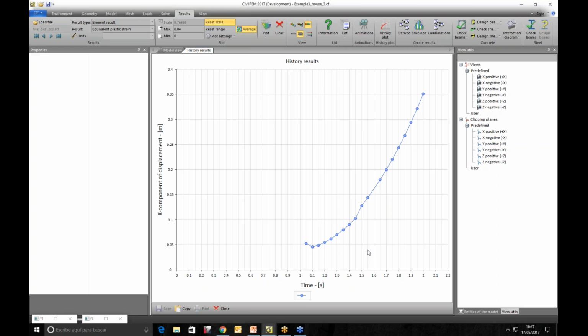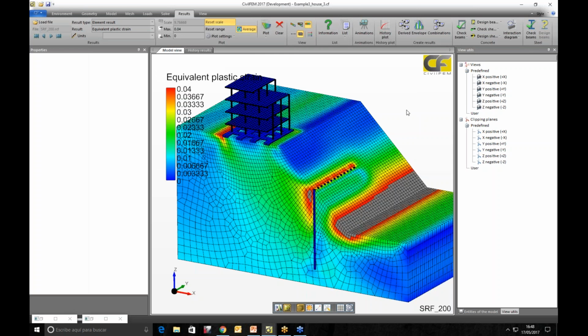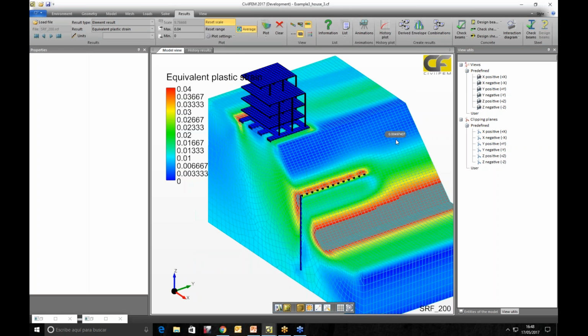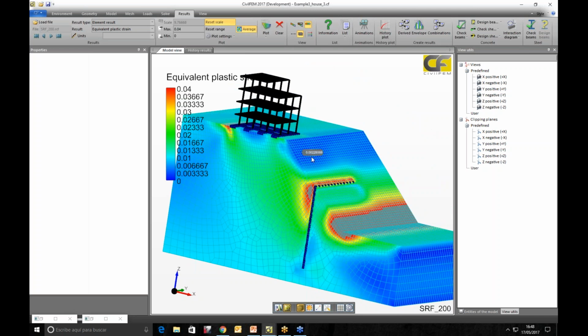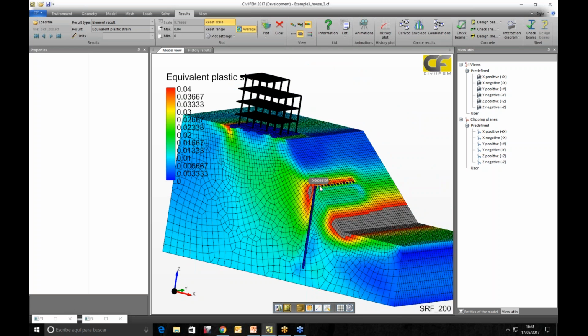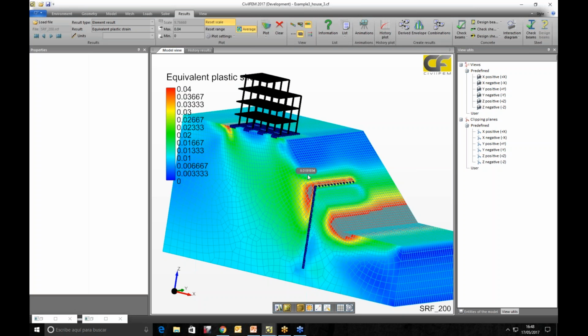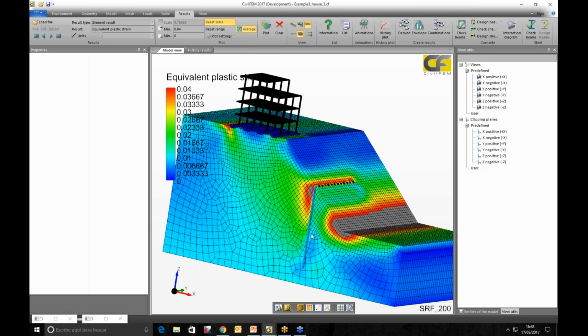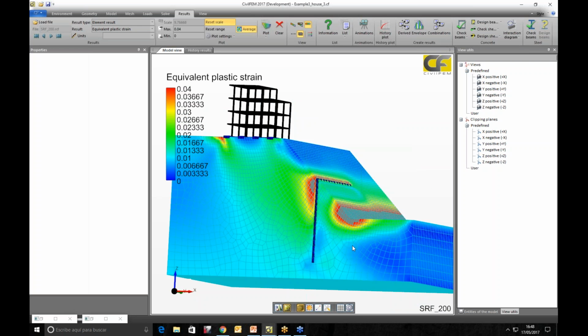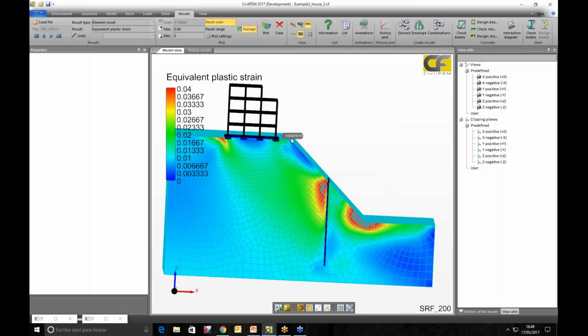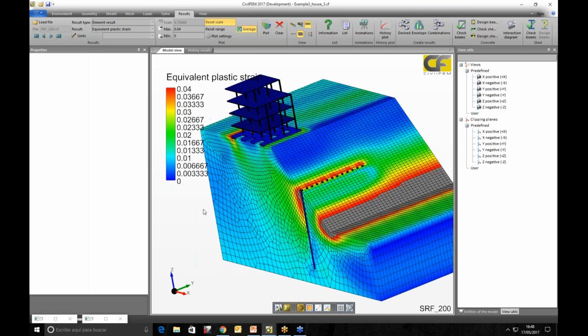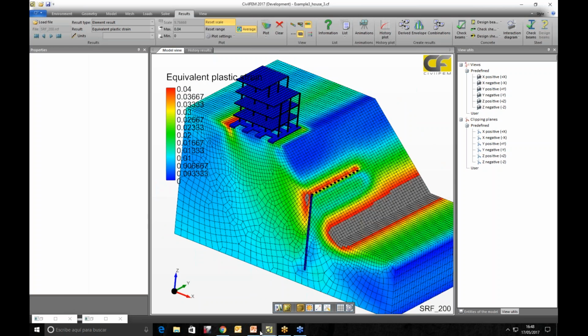So we have improved a little bit the displacements, but well, didn't improve much, and we are having, after that safety factor, bigger displacements that are not allowable for this model. So we could decide any other configuration and any other possibilities like reinforced air, doing inserts of different bars here, anchors, modifying, just adding here a weight, modifying the slope, and see the best solution of them.